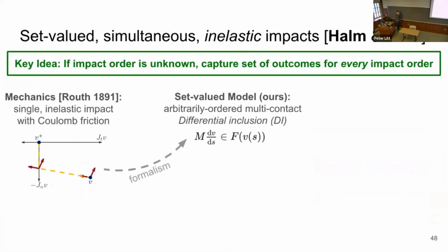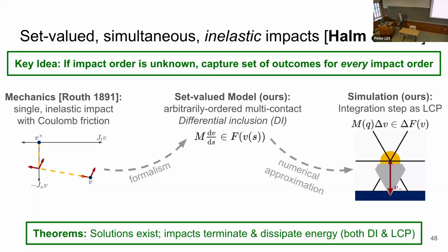So from this notion of inelasticity, the set considers active contacts as ones where applying a normal force would dissipate kinetic energy. Basically that means that there's still incoming velocity. So pushing apart, just from force times velocity as power, would reduce kinetic energy. And that's very fundamental to how we're getting this net dissipation over the impact process.